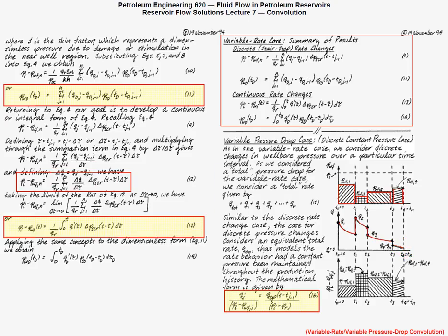Okay, well, hopefully that gives you an idea of what that'll look like. And then we have to do the same sort of stepping thing where we take and we calculate the pressure difference at each step. And of course, the first one is the difference between PI minus PWF. The second one is PWF1 minus PWF2. The next one is PWF2 minus PWF3. And then the next one is PWF3 minus PWF4. So it's sort of a similar stepping system.